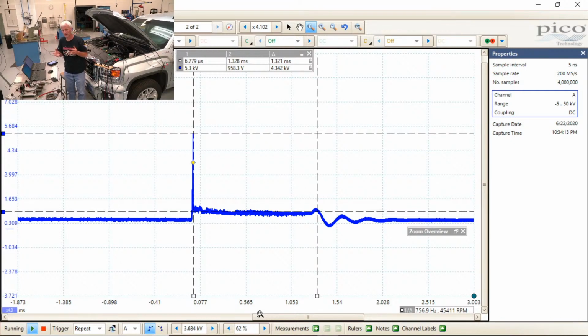Well, there's still a little bit of energy left. It went from 1,000 to nothing, and now it's got to sit there and wring that energy back and forth and use it up. I don't know if I'm 100% accurate on this, but a lot of times you'll say when you wring this thing back and forth, you're using up that voltage by oscillating it back and forth through the resistance of the coil itself. And then it's ready for the next time around. That's a typical secondary pattern.